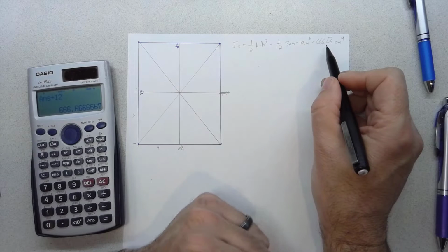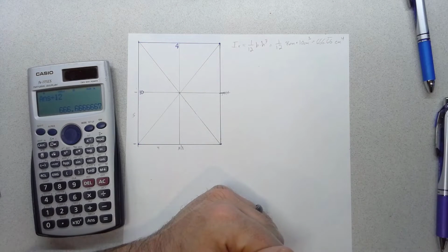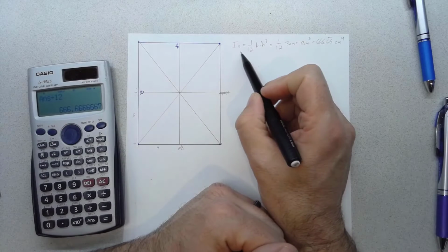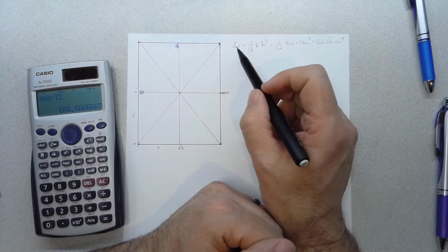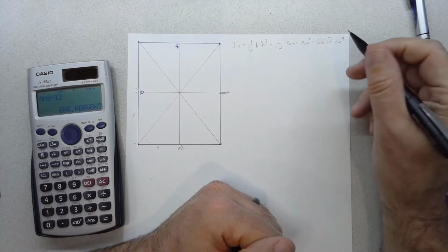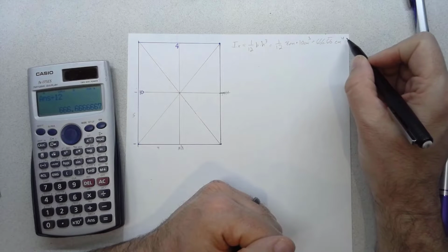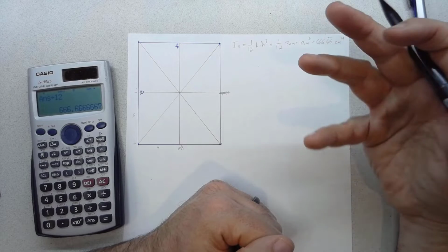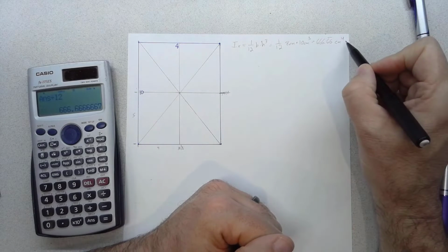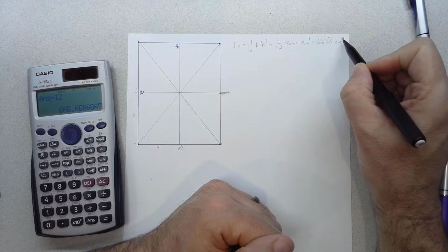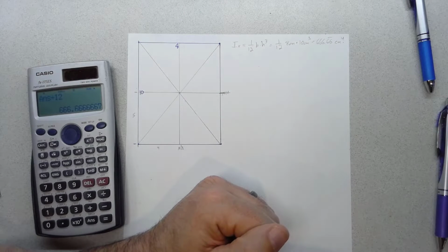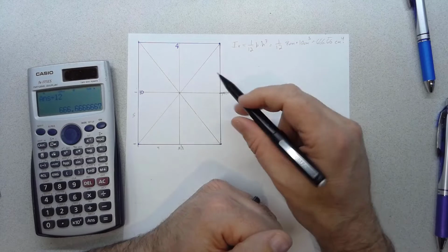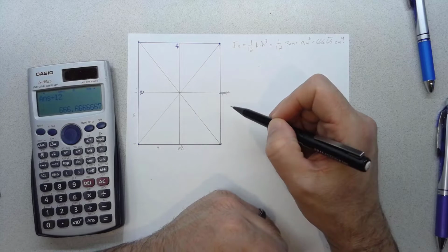And so obviously that's not a physical dimension, right? There's no such thing as centimeters to the 4th that makes sense. And that comes back to me saying this isn't really a property that you can directly measure. It's useful. It functions in the equations the way we need it to, but you can't have a centimeter to the 4th power, right? We can go centimeters, that's a unit of length, centimeters squared, that's a unit of area, centimeters cubed, that's a unit of volume, centimeters to the 4th, that's useful, and we do need to use that because our units will cancel out correctly when we're doing the moment equation or shear equation, etc. Okay, so that is I for this particular shape about this centroidal axis.